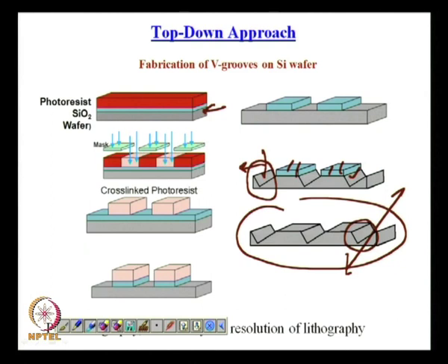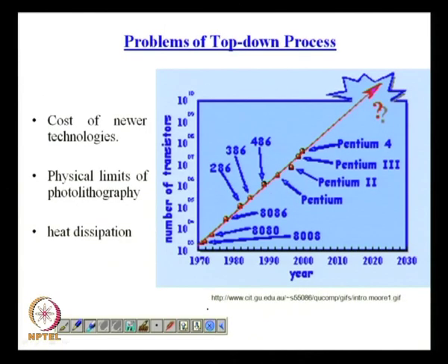So, you will hear of facilities like class 100 atmosphere, in which, I think the definition is, there would be less than 100 particles of 10 micron size or more in 1 cubic meter of air. So, there will be filtering of air, specialty chemicals and processes to clean the silicon and so on. So, we see that it is becoming more and more a process which requires a lot of money and investment and specialized training.